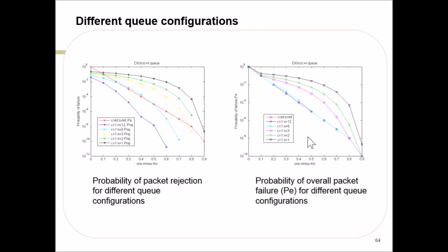We calculate that LLR. And the processor, going back to that orange processor, was simply taking the minimum of all the numbers. We're taking the minimum among the absolute values, and then when we're computing the output for a check node, there is a simple equation. Once we compute min 1 and min 2, we assign them to the outputs. Most of the outputs would have min 1 as the output, and only one would have min 2.